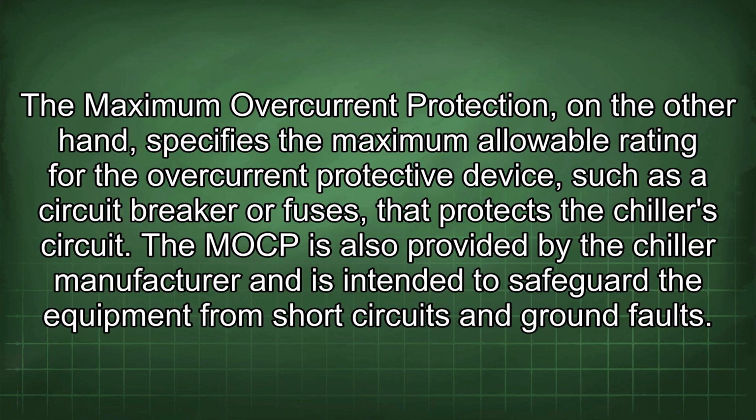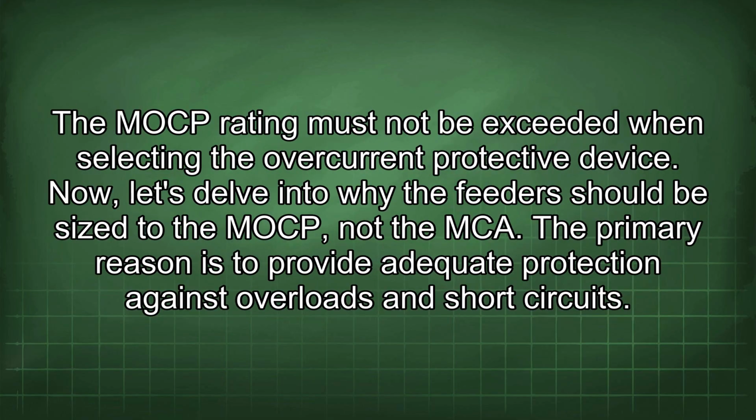The maximum overcurrent protection, on the other hand, specifies the maximum allowable rating for the overcurrent protective device, such as a circuit breaker or fuses, that protects the chiller circuit. The MOCP is also provided by the chiller manufacturer and is intended to safeguard the equipment from short circuits and ground faults. The MOCP rating must not be exceeded when selecting the overcurrent protective device.